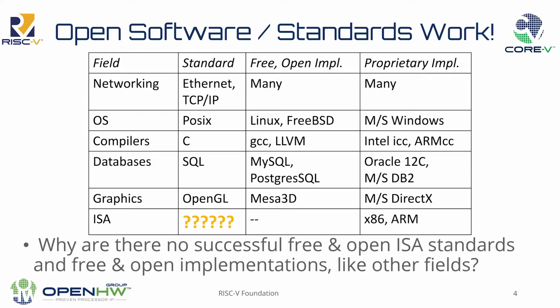So it's been interesting to see that there really has not been an open specification at the ISA level. Instruction set architecture, by the way, that's what an ISA is, if that's new to some of the folks. I'm making a couple of generalizations in here that I probably shouldn't. And RISC is reduced instruction set computing, as opposed to a CISC architecture, complex instruction set computing. x86 is an example of a CISC machine, although they've done lots of things to it to make it feel and look like the attributes of RISC architecture, but it's a much, much bigger ISA. So we'll talk about some of those differences later.